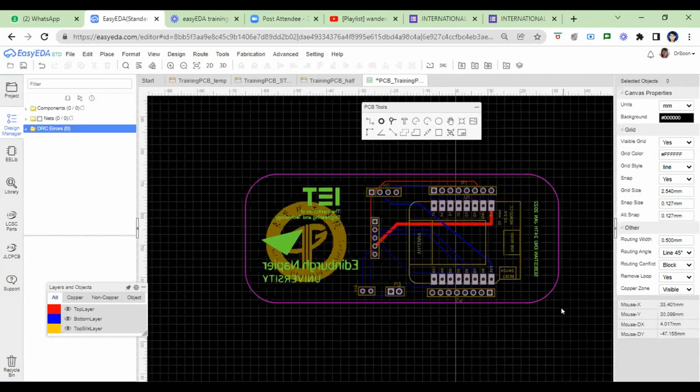Okay, all right, so to ground all the noise from the surrounding, to have a good grounding, we need a copper layer, a full copper layer. So where to get the full copper layer? This is the very critical part, because when I first learned this software, I didn't know how to do it. So let me show you how.